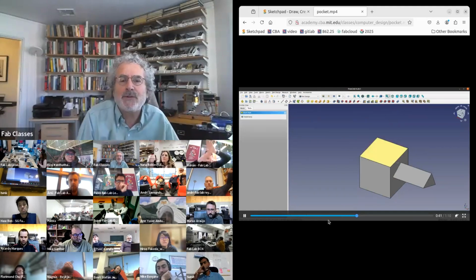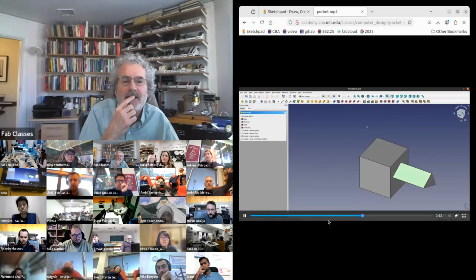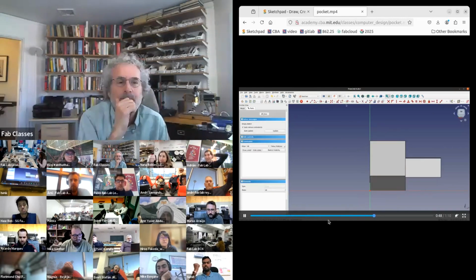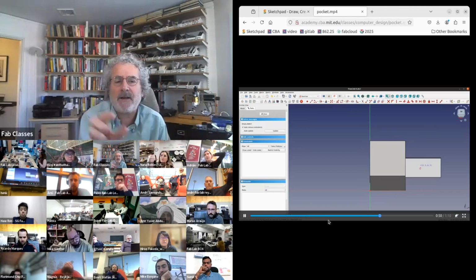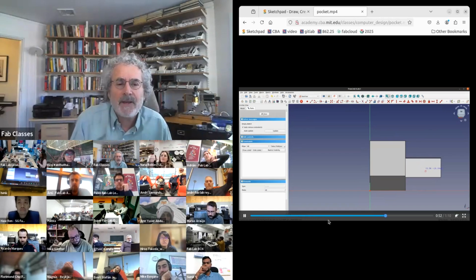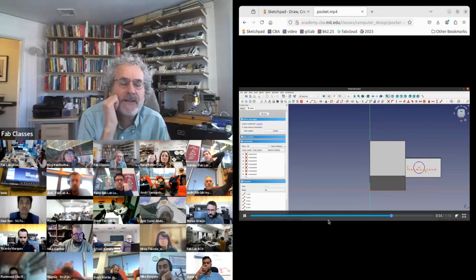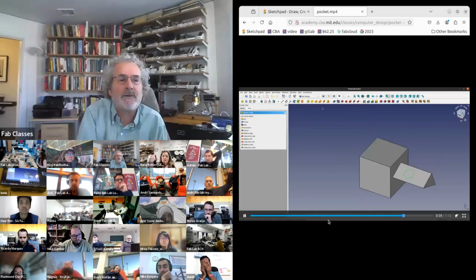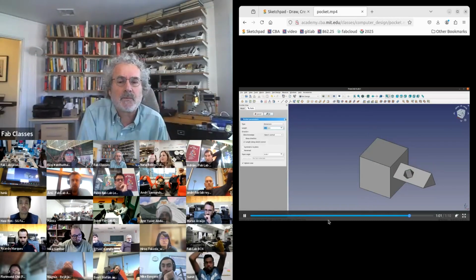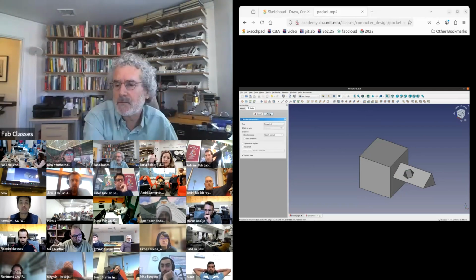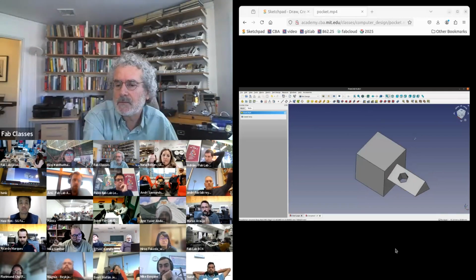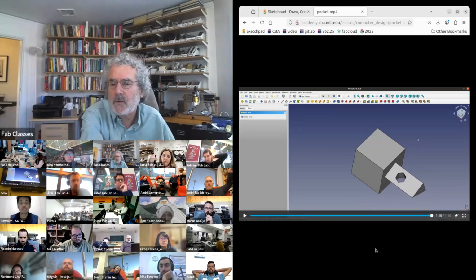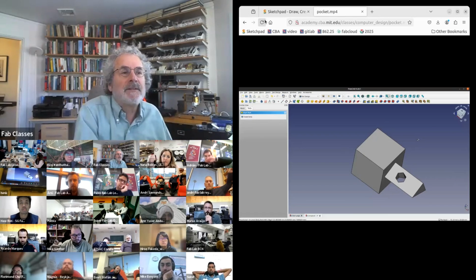I'm going to do an extrusion, but I extruded it on the face. Now I'm going to pick another face. I'll start working on that face. And I just pick the face. I don't have to specify where I am. Now I'll make a sketch on that face. And then here I'm going to do the opposite. I'll pocket. I'm going to cut it out.